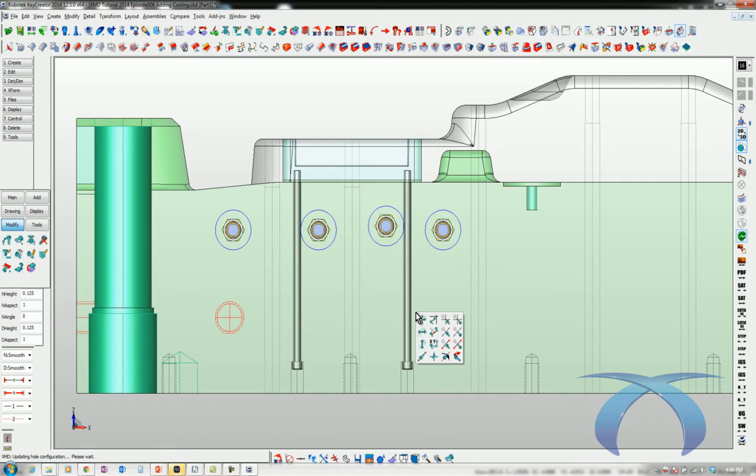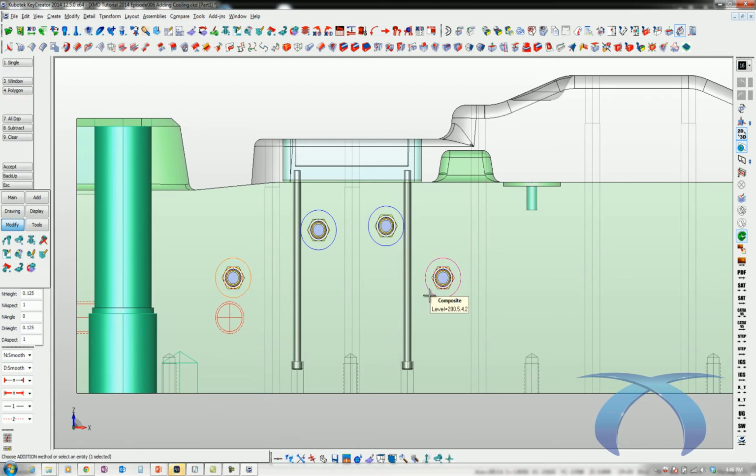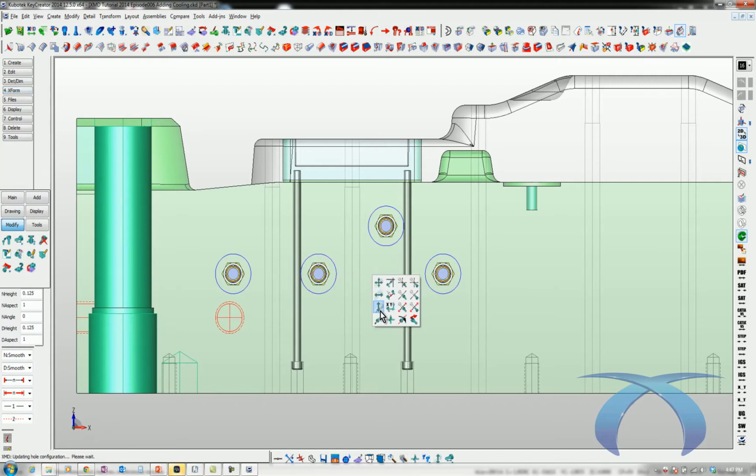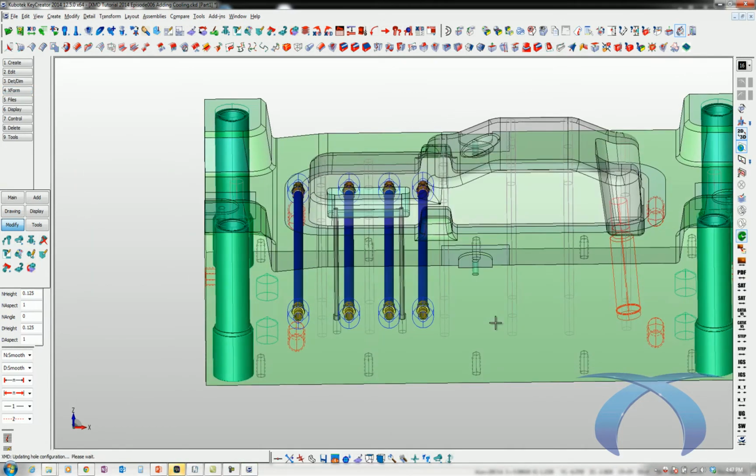Now I've just made a decision though, maybe I don't really like that height of them, maybe I want to bring them down here. I'll show you why in a little bit. So I can go ahead and move them down. And remember, when we were talking before about the vertical move, what's really nice about it is I can pick at the center of this line to ensure that this line moves down. I'm using a vertical command, so no matter where I place my cursor, it still only goes straight up and down. I'm going to move them all up another 1/8 of an inch. I want to be a little further from that eye bolt. Okay. And then we'll move these other two down as well. Okay. So it's very easy to move and manipulate and reorganize the way your circuits look.